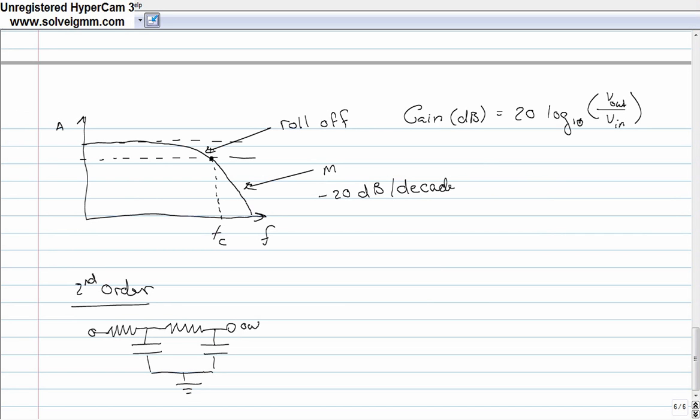And that's it. This is now a second order filter because it has two filters in it that both accomplish the same thing: R1, C1, R2, C2. So that's a second order filter, and that changes some of the behaviors. First of which being, it changes the equation to determine cutoff frequency.